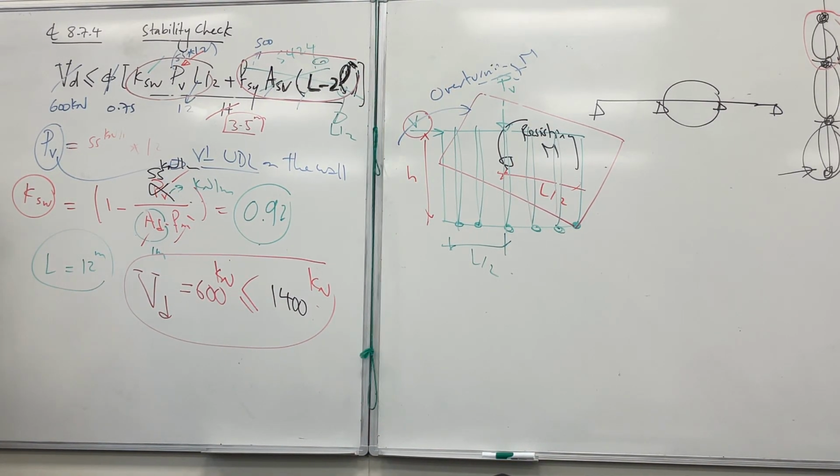You can't necessarily say that, because on the plan here you've got shear. This already makes it 600, so you can't say it's only acting on one. It's not a moment, it's a force. If you flip it, it's essentially acting over the whole 2.5. BD is a shear force.